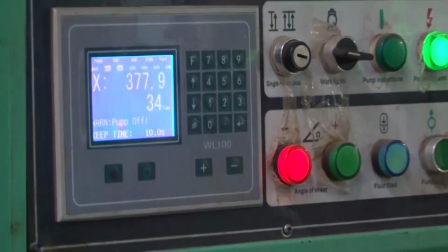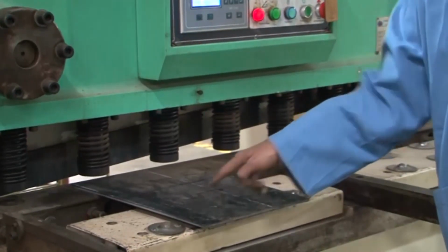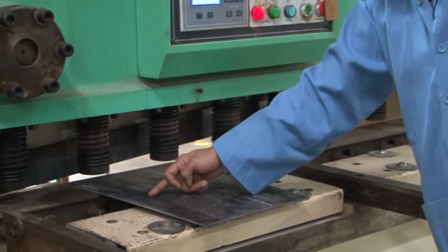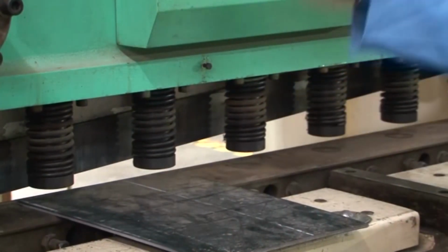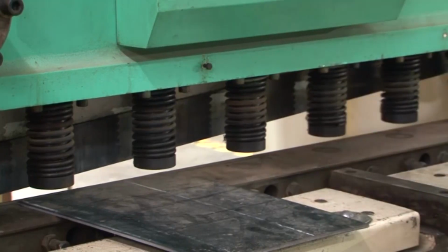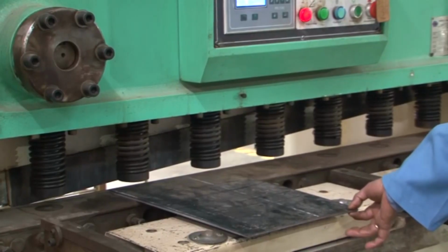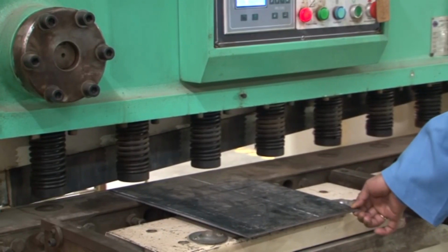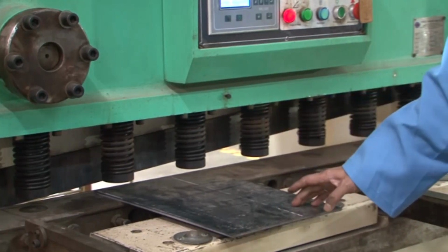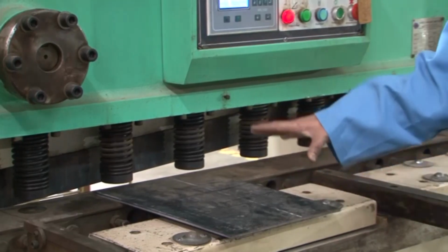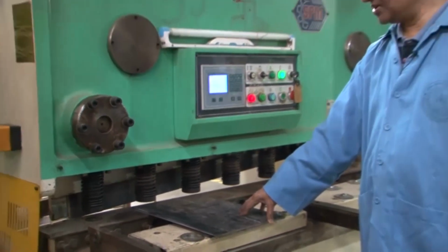So, according to your requirement you can adjust the length, and this width that you can take. For example, here we have taken a certain width. Now, the length is important for us. We can cut it in small pieces or in bigger pieces, that depends on how much you are setting in the x value. We have a plate whose thickness here is 6 millimeter, but you can go up to 8 millimeter. Okay. So, steel plates up to 8 millimeter thickness can be sheared off, and as you understand the shearing force required here will be very high, and therefore, hydraulically operated machines are used.